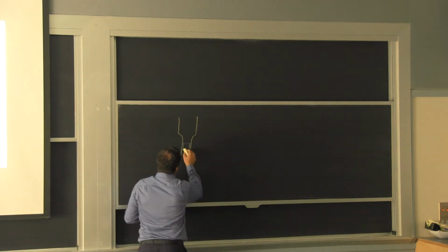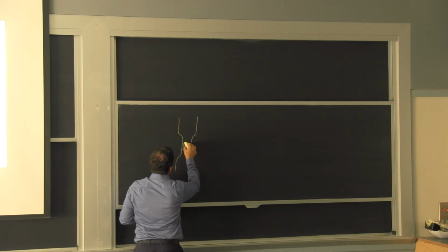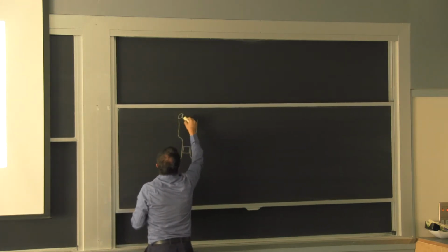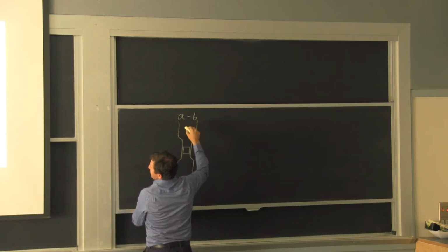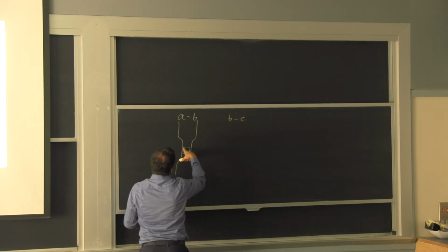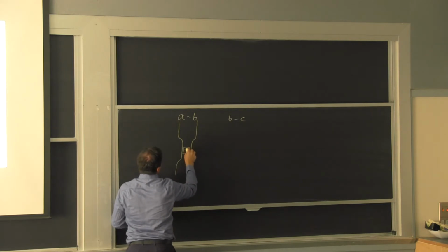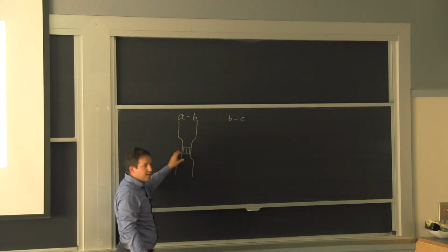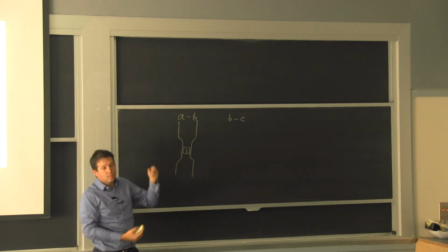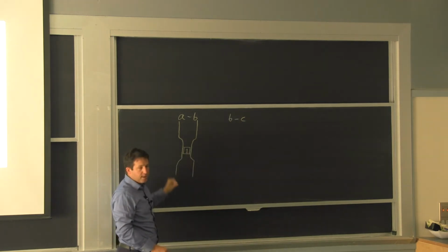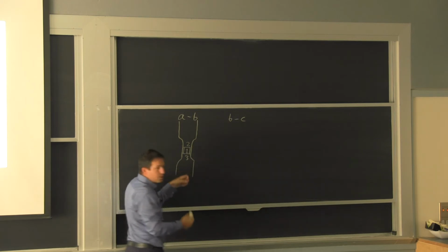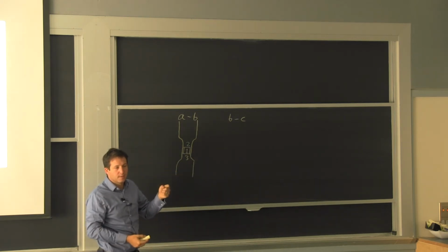So what happens in practice if I have just a little instability at the beginning? So we're going to say in the A to B zone. And then we're going to be in the B to C zone. What happens here is the strength goes so high. So if I have this at the beginning, this plasticity is going to stop, because even though I've lost a little bit of width, I gain so much in my strength that that's enough. So then I'm going to deform a little bit here, and deform a little bit there, and it just keeps going as a regular process.